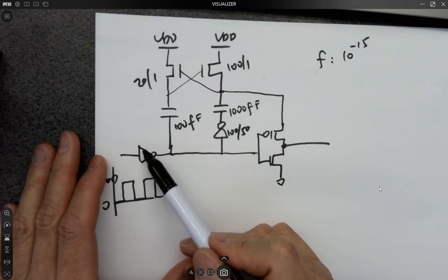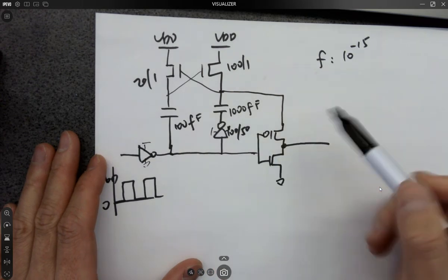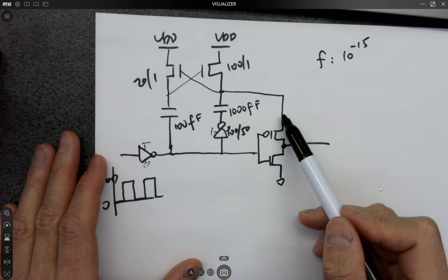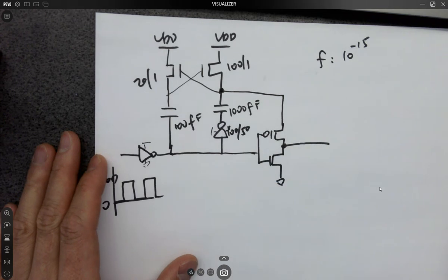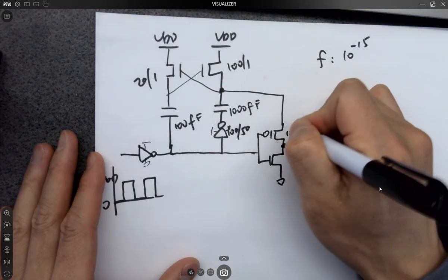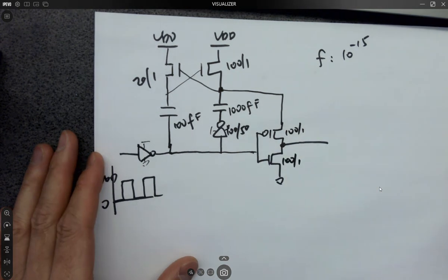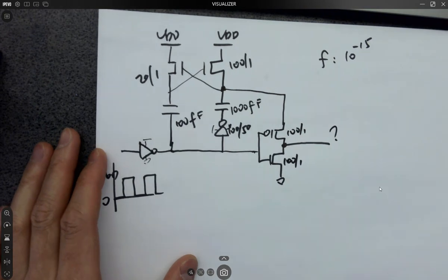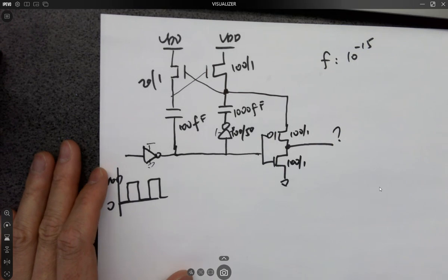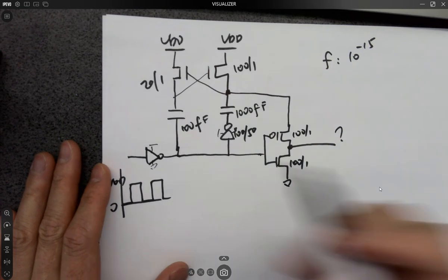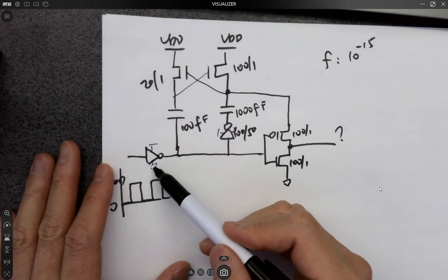Remember in the schematic you have to. So actually they have power rails, right? You'll see this one has a different power. This is shorted to VDD, right? So the power is not VDD, it's over here. Very good question, okay? Notice the difference. It's going to ask you what the output looks like. I didn't label VDD and ground for these inverters, so you should know that by default, they are shorted to VDD and ground, right? By default.